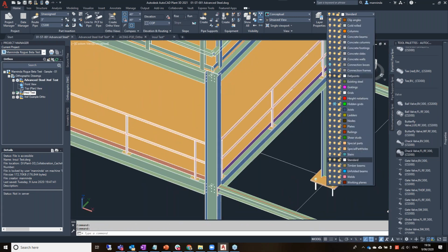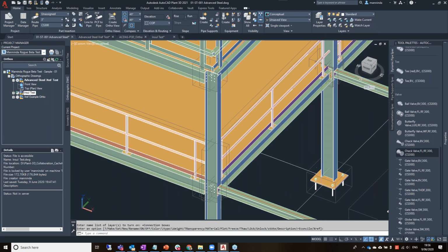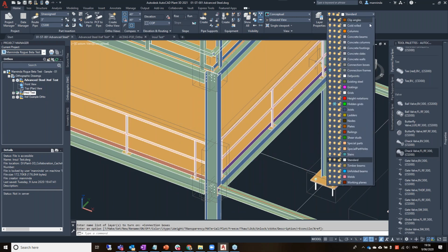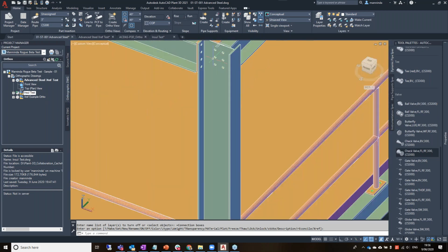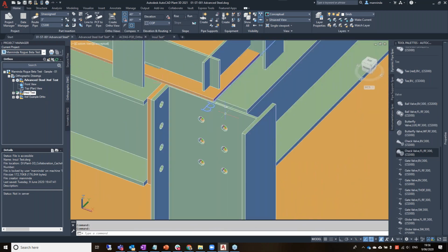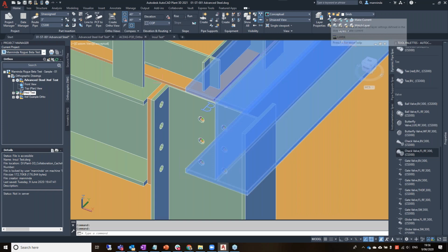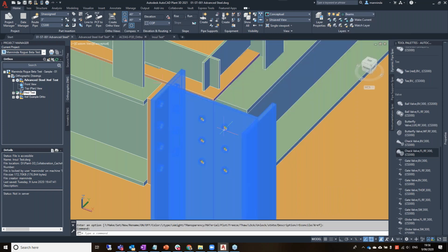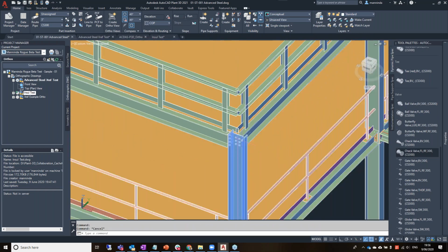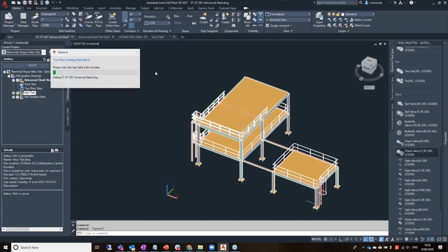The other one is connection boxes. Each of these wireframe boxes refers to a connection type. So I turn those off as well, and you can certainly probably script or control that. And you can see here, that's a grid marker. You can turn that off too if you wanted to. I don't think there's a way to go lower, since those holes are part of the beam. Let's save that and see how that comes out, with 3 minutes to go.